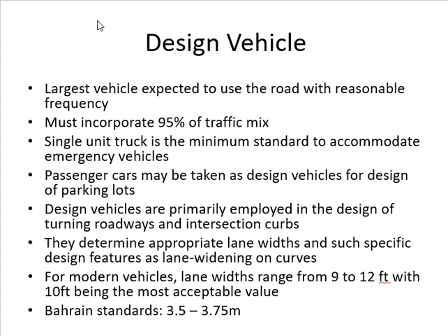You can take the next best thing. If I have a very, very big truck which has 1% and a smaller truck which has 7%, the very big truck can be ignored because I will just ignore 1%, which is allowed. But the other truck which covers 7%, I cannot ignore, because then it is more than 5%. Got it? So any vehicle with less than 5% of the traffic can be ignored even if it has the biggest size.